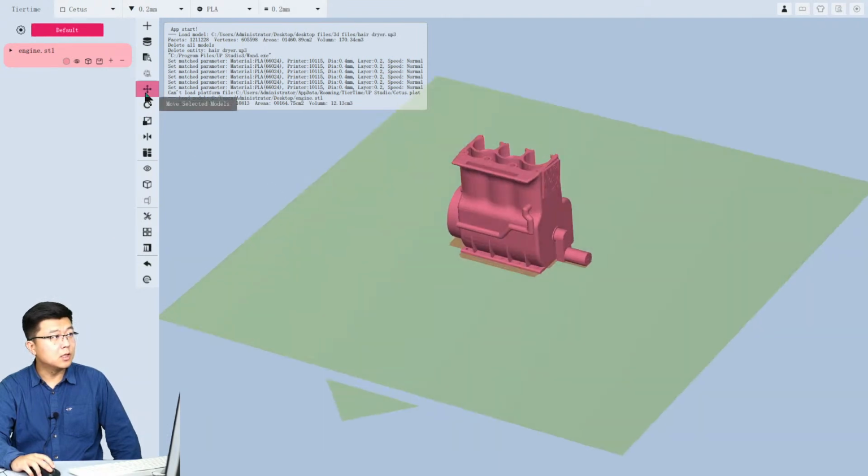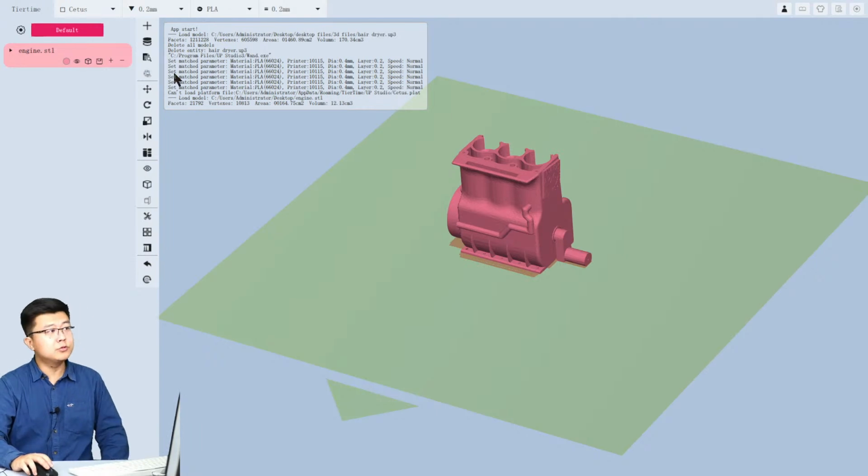And then we click this, which is called slice model. This is a preview, and these two are very similar. But the preview only does partial calculations, while the slice does a complete calculation. The preview is actually a little bit faster than the slice, but it will not show some of the slice toolpath function info, such as the seam location. It's not shown in the preview.